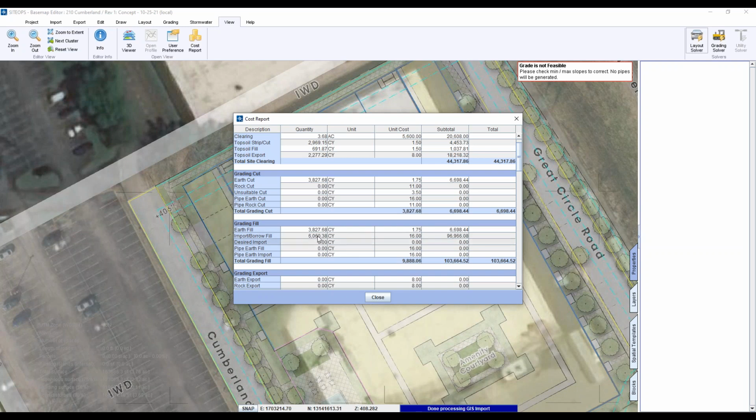Now, always bear in mind to check whether you're using your shrink swell on that or not. A lot of times I'll do it straight up without, and then I'll add it in the estimate. Yes. So how often, if an architect gives you something, do you raise it and lower it 2 feet and rerun it for the estimation, just to compare prices? Or are you looking at multiple iterations for each of these projects?